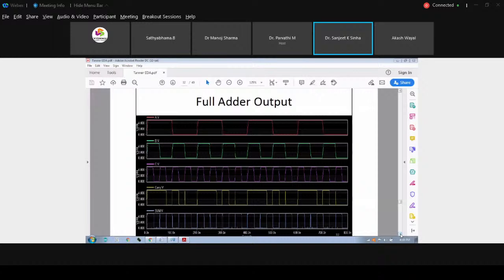Yes, this is quite interesting. 4:1 multiplexer. This is the typical 4:1 multiplexer. If you are going to design it, it will take so many AND gates. You can see 4 3-input AND gates, 2 NOT gates, and 1 4-input OR gate. But if you design these things using transmission gates, and generally people prefer multiplexers using transmission gates.